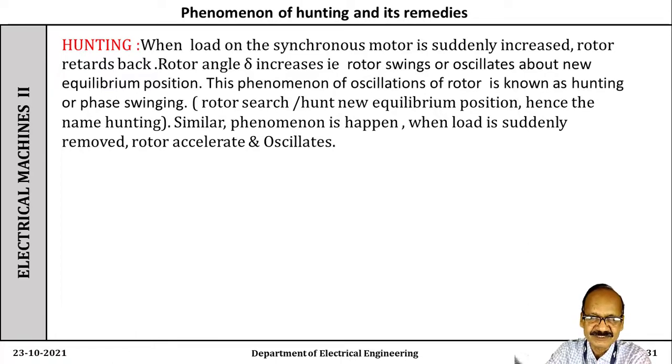But if the load on the synchronous motor is suddenly increased, the rotor falls back and oscillates about its new axis for some time before coming to rest. But because of the moment of inertia of the rotor, it takes some time to settle to its new position. These oscillations of the rotor are known as hunting, or also swinging of the rotor. The rotor surges, in other words, it hunts for a new equilibrium position, and hence the name hunting.